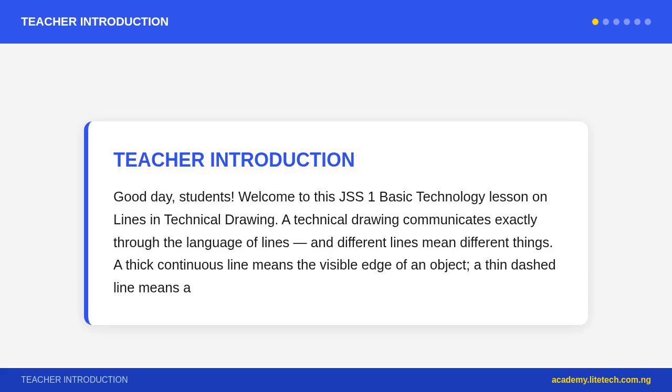1. Continuous thick line, outlines/visible lines. Thick, unbroken, solid line. Used to show all visible edges and outlines of the object. This is the most prominent line in a drawing, it shows what you can see of the object. Pencil grade, HB or B, line weight, approximately 0.5 to 0.7 mm, thick.